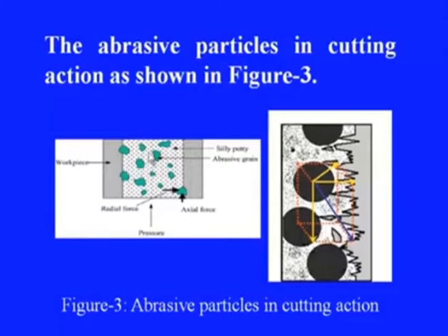So, these are the abrasive particles. They are immersed in this media, which is pushed under pressure, and while coming through, some of them will remove or cut some of these asperities like this, and this has now become a tiny chip.